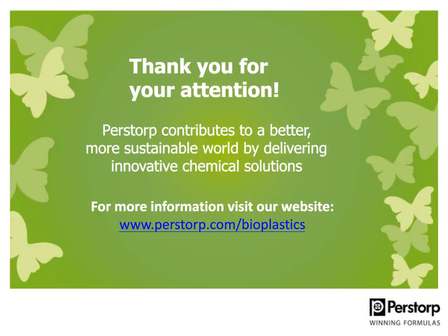Compared to PLA, for example, which is quite sensitive to hydrolytic degradation and can catalyze its own degradation, PCL won't. So it's really linked to this. When it ends up in the right conditions in the soil and you have microorganisms, that will initiate the biodegradation. And as long as it's in use and under conditions which are not challenging the general properties of the product, it will remain stable. Thank you.